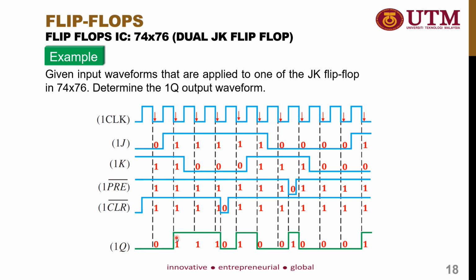Okay, so this is how you can solve the problem of asynchronous flip-flops by using the flip-flop IC. For flip-flop ICs, you need to know the model of each IC, 74x74 or 74x76, and you need to remember whether it is positive or negative edge triggered.